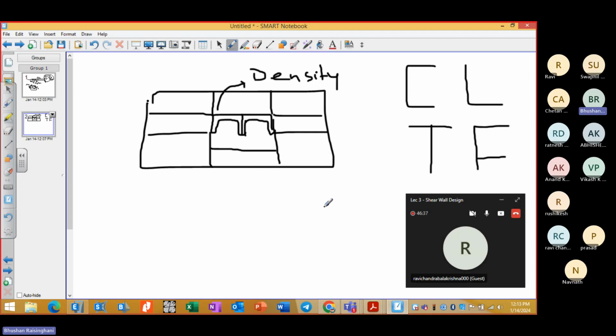There is no such clause to give connectivity to the periphery, but that is one type of arrangement that is done if the first mode is torsion. If the first mode is not torsion, then you will keep just the core. But if the first mode becomes torsion, then you need to check how much force is taken by the core wall, how much force is taken by the frame, and what arrangement you have done. It needs to be thoroughly checked if it is just the central core.